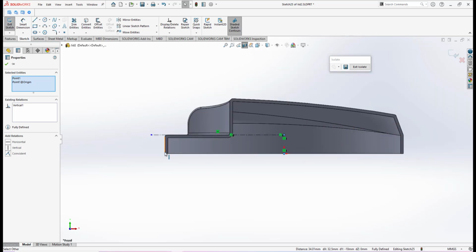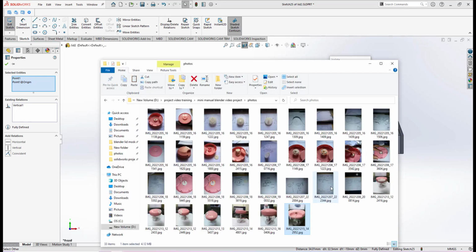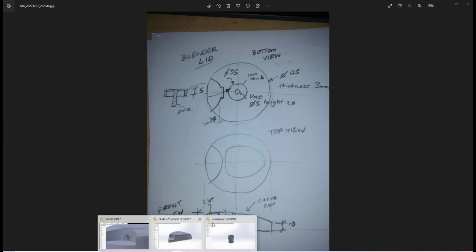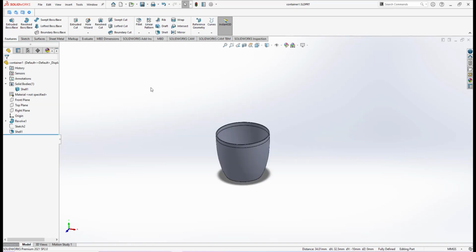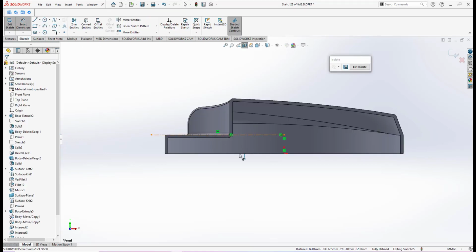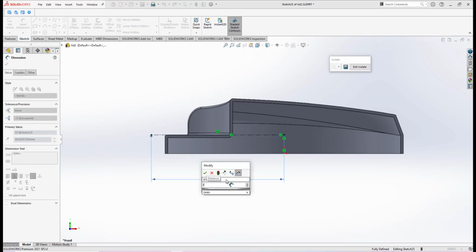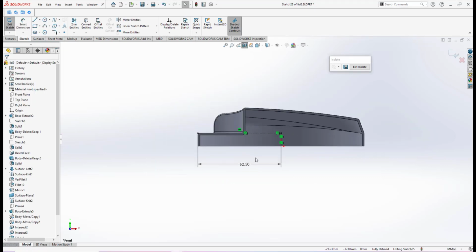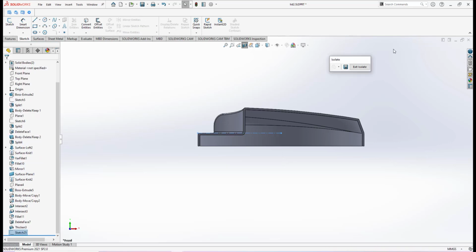and this line is the radius, because as shown in this image, the diameter of our lid is 125, so our radius will be 62.5. So in the sketch here, I put the dimension, the radius is 62.5. Right, so then I exit the sketch.